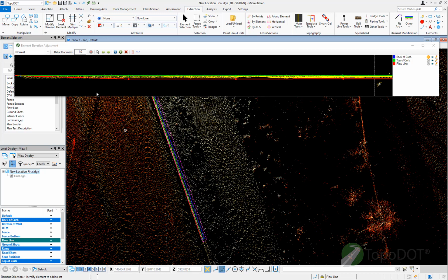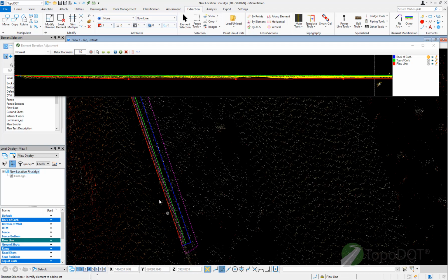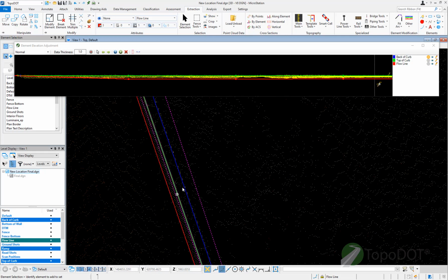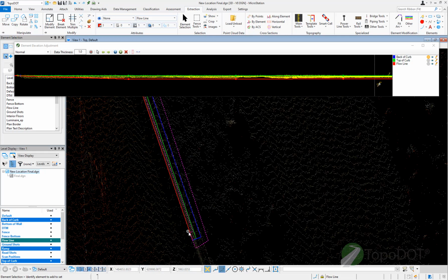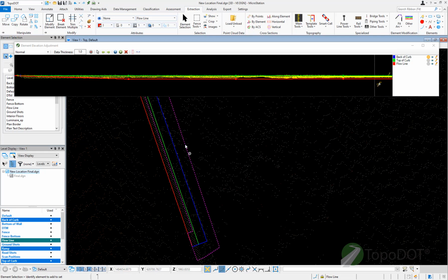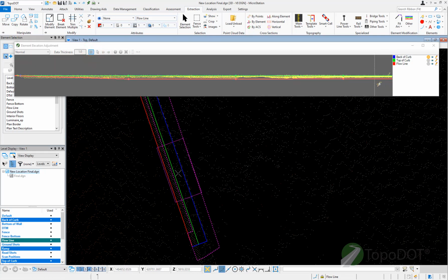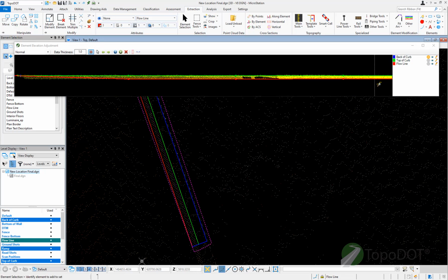So right away you can see here that it finds all three lines that I've created or that were created, and is using the back of the curve as the center of the cross section that is showing me here. But if I want to change that cross section to maybe focus a little bit more on the front face of the curve, which is not the case here, as you can see the pink area right here is what is showing me on this view, I can either move or shift my path towards the front face of the curve a little bit more,